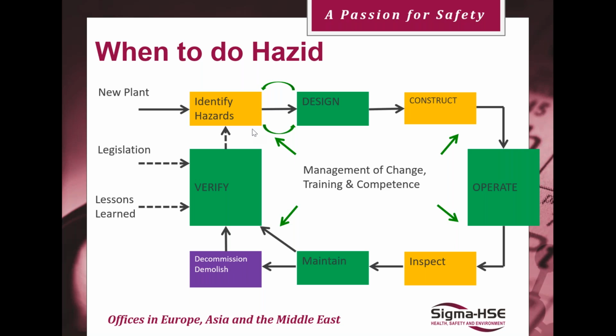You know that it is toxic, you know it's denser than air, and that can be used to inform your design somewhat. At least you'll know that if it is toxic, it's a good idea to put it in a place that's not terribly crowded, for example, because a loss of containment would involve a lot of people. So we can at least make some early decisions.